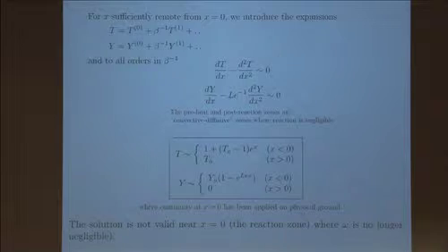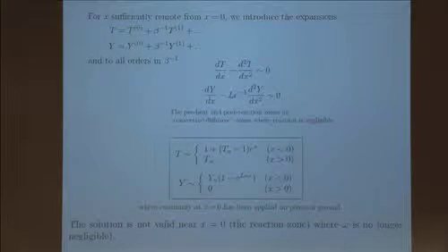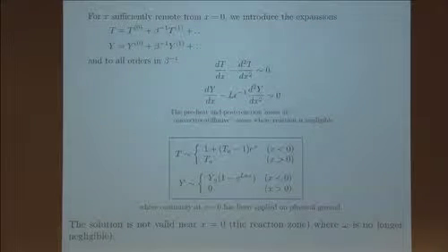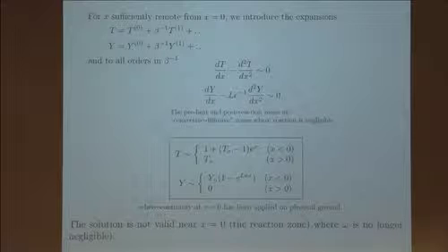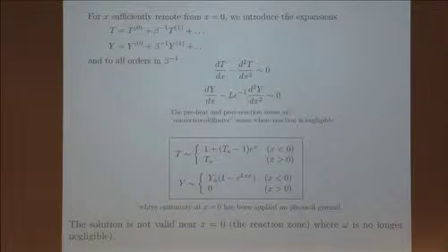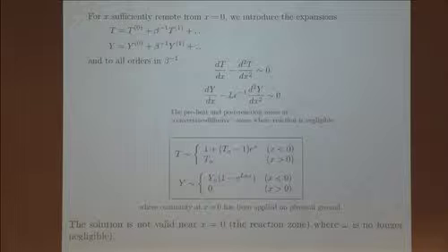And so that's a good solution to leading order, which is valid in the preheat zone and beyond the reaction zone. But this solution is not valid near x equal to 0, because there the temperature T is close to TA, and we have seen that when the temperature is close to TA, within 1 over beta, then the reaction is important.